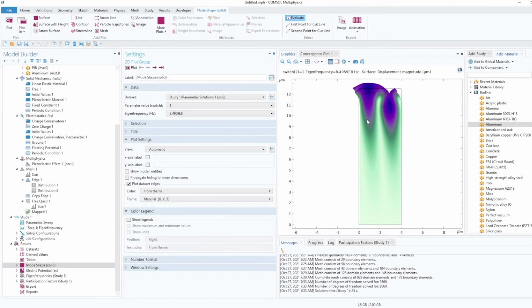But before that, if you see, this is the anti-resonant frequency, and it's around 8.4, like you can see 8.4 times 10 to the power 8. So around 850 megahertz. Okay. So if we change these, its shape will change.